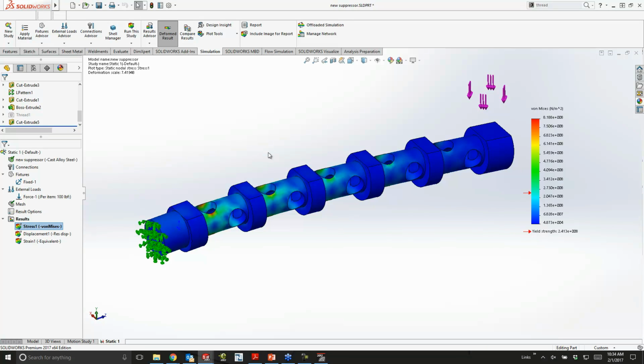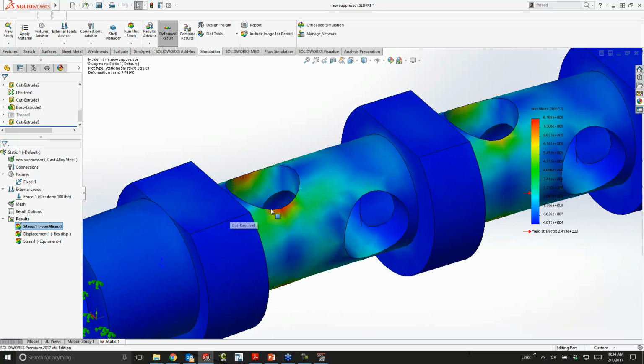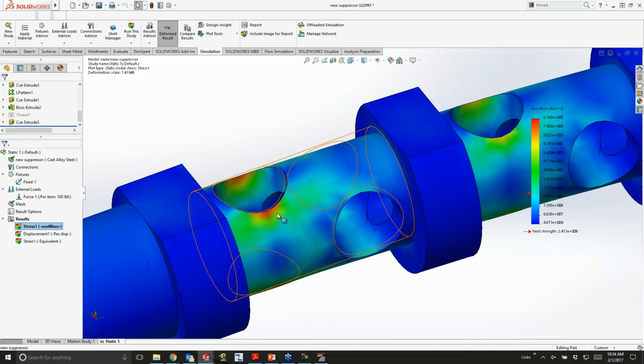Now this can also be done with a thermal study. We can run the thermal analysis, see what's going on with the heat as this thing heats up, and it is definitely going to heat up, to see what that's going to do with the assembly. We don't want it to crack as this thing heats up, and the heat just gets intense in these designs. So the thermal aspect of it is going to be very important to handle. Looks like we have possibly some stress concentrations or some stress issues around these holes. So when we go to actually finalize the geometry, if we know that's where the hole wants to be, we may put a little bit of extra time and effort into optimizing the shape to make sure that the stresses are handled correctly.